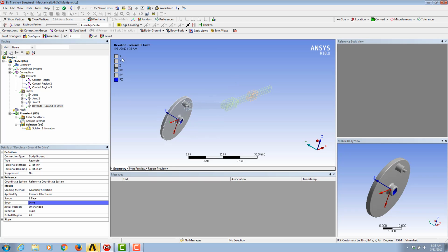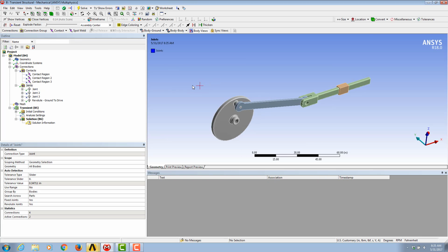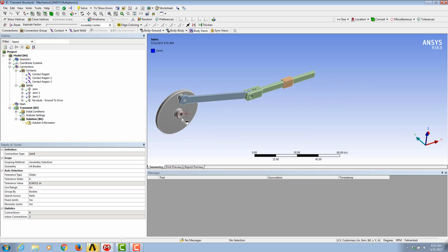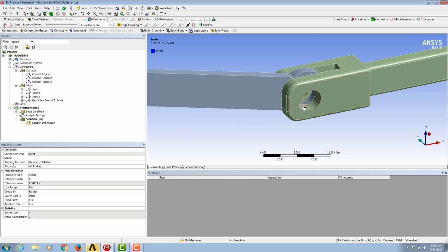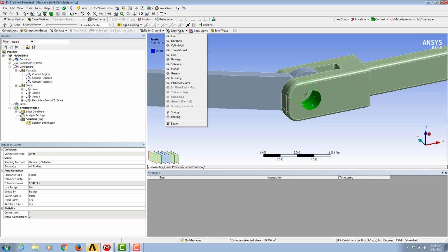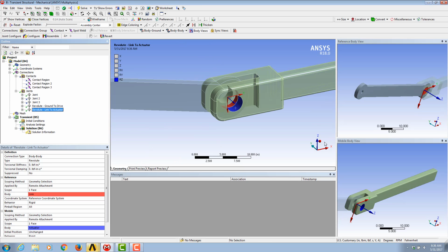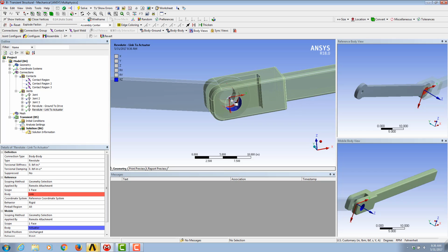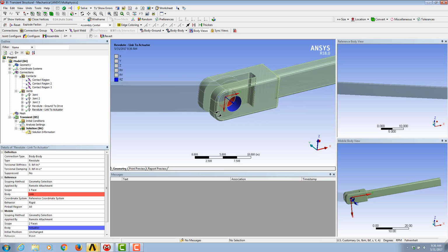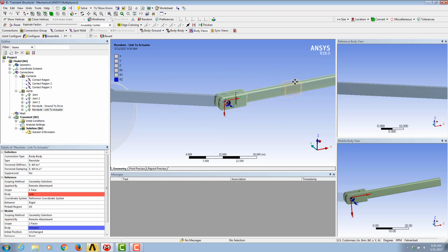And so just keep on building up this assembly. And so I have this properly defined. I have this revolute joint properly defined, so I'll just work my way to here. I'll pick these 2 faces, go back, specify this is a body-to-body interaction, so I'll specify that this is a revolute. And if I want to, I can go back and clean up or add this additional face. So if I click on my mobile side, if I click that, go back, hold Control, left mouse click on that other face, and then hit apply. I've now included all of the faces in this clevis joint.